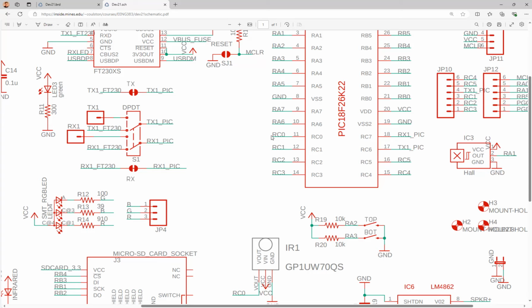We're going to click the button and turn on the TV. You need 32 bits though. Can you do that many? I don't know how many bits are in there for the UART, but like 8 bits. Yeah, it's usually just bytes. So like the buttons on the remote over there, you can actually see it. If you don't use the IR LED on your board, just use that one and try it and see what kind of code you are receiving, and you can look at the code and then encode it, and send it through that one. It's going to do the same thing. It's going to control that one easily using your PIC. Yeah, it's going to work.